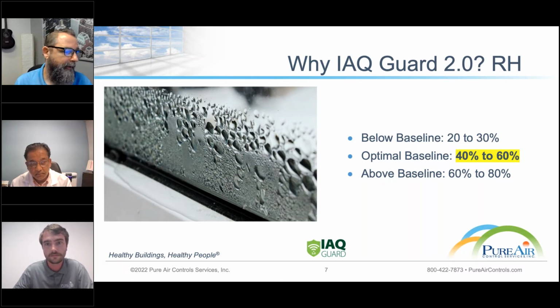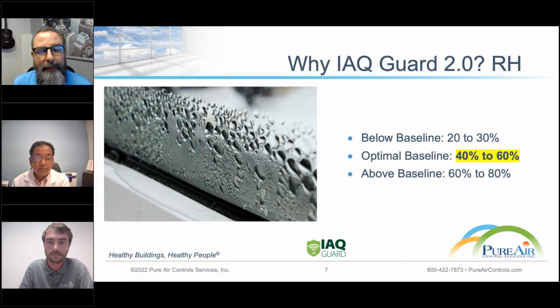I think another thing to look at with relative humidity is if inline equipment, Nick, and maybe you've seen this doing some of the HVAC hygiene assessments out in the field, but if inline equipment like reheat coils, VAV terminal boxes become fouled or obstructed, then the airflow is decreased to those certain HVAC zones.